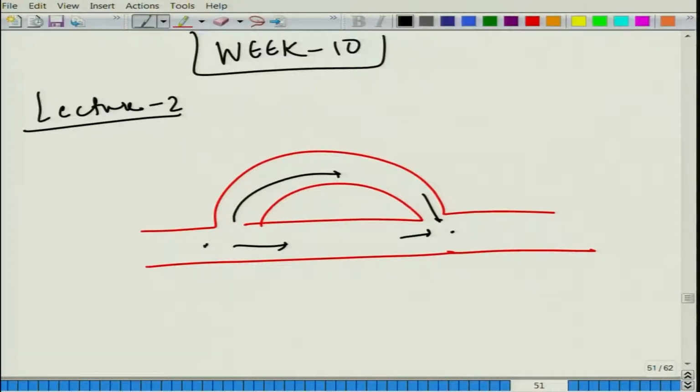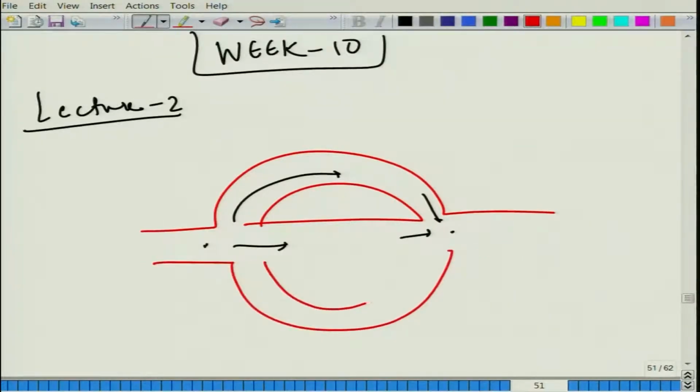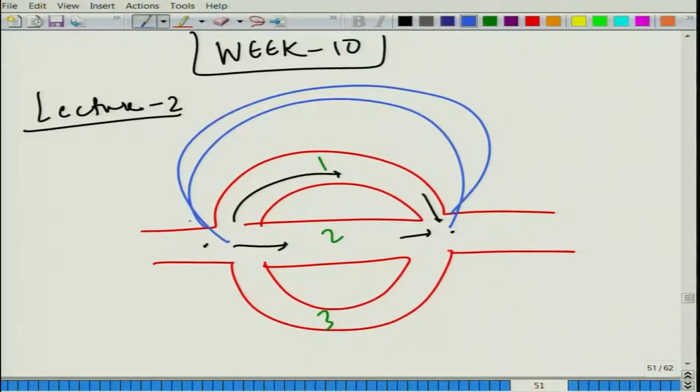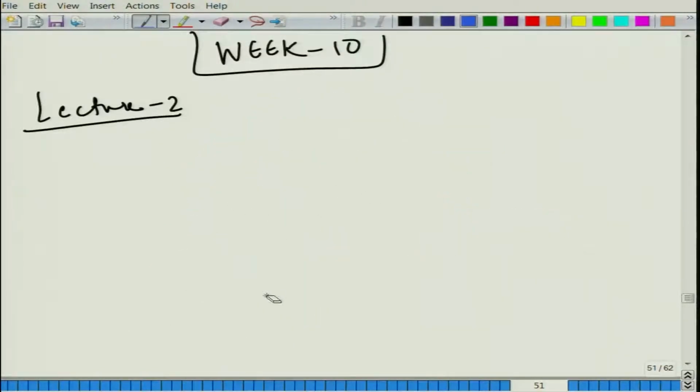Then there are a bunch of papers which talk about the modified Herschel-Quincke tube, in which case you have even more tubes attached. For example, things like this one. So, they are basically like 1, 2 and 3 pipes, or they could be more. There could be n number of such pipes, each with different lengths, and the constructive or destructive interference causes resonances. So, let us get back to our simple two duct configuration like the one that was presented here.